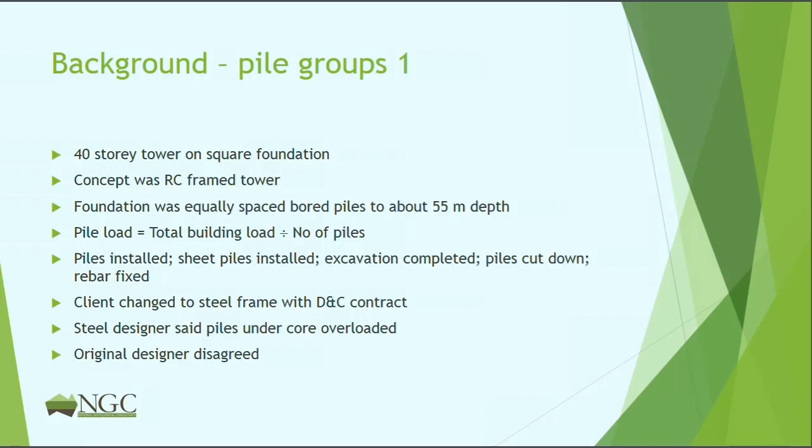There was a requirement to build a 40-story tower on a square foundation, and the concept was for it to be an RC frame structure. The structural engineer decided that the foundation would be equally spaced bored piles, about 55 meters deep, and he said, okay, I'm going to determine the pile load by taking the total load of the building and dividing by the number of piles. A very simple approach that says all the piles are uniformly loaded, just an executive decision.